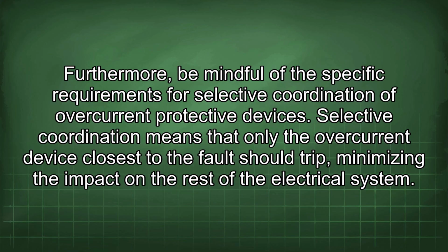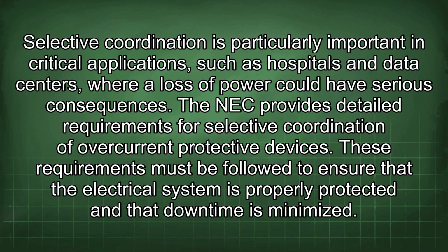Selective coordination is particularly important in critical applications such as hospitals and data centers, where loss of power could have serious consequences. The NEC provides detailed requirements for selective coordination of overcurrent protective devices. These requirements must be followed to ensure that the electrical system is properly protected and that downtime is minimized.